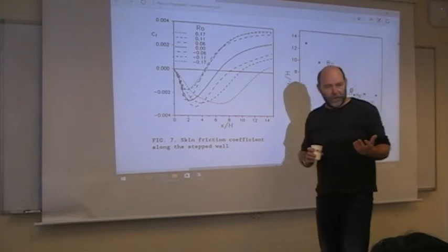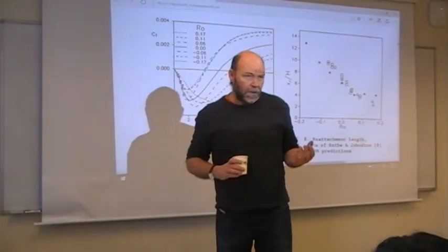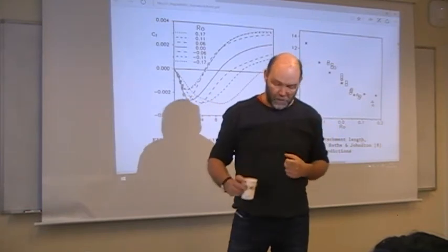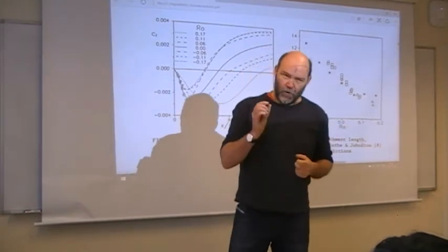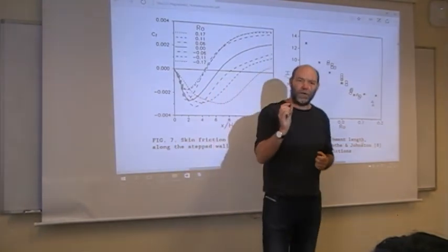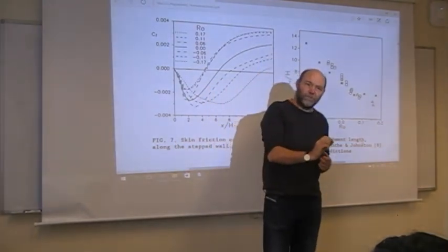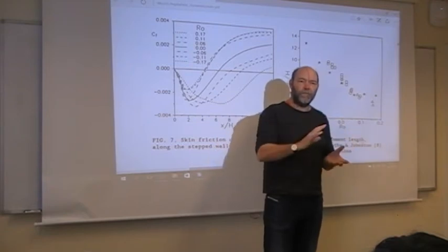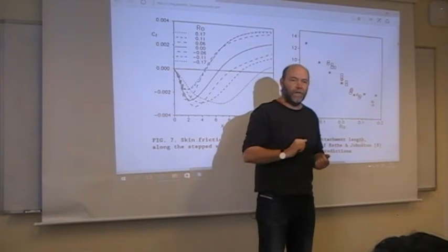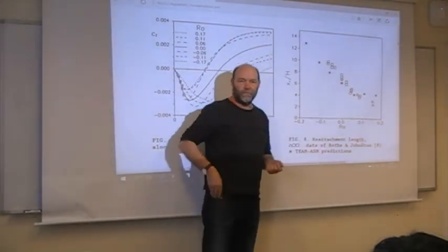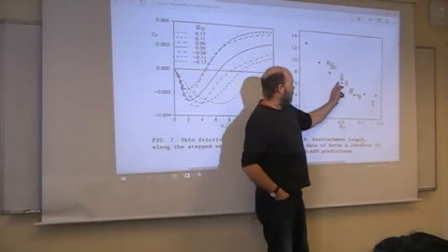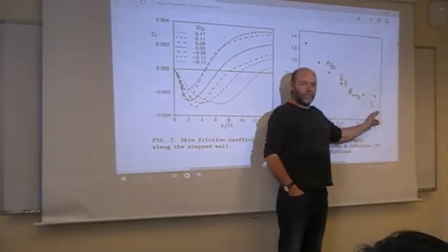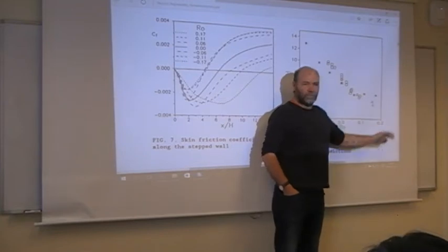Remember what happens on the rotating side: you increase the turbulence. The turbulent activity gets stronger, meaning your smallest turbulent scale becomes smaller and smaller. You have to use more and more cells to resolve the flow. Because they run the same grid. Exactly. So they should have used a finer and finer mesh to really resolve it correctly. So here they are in trouble.